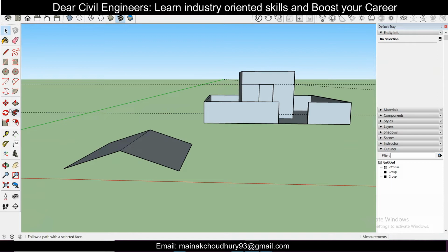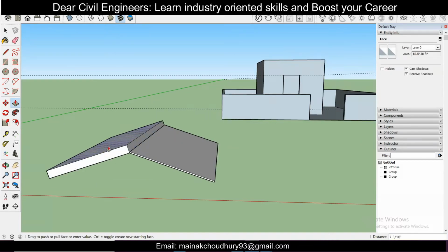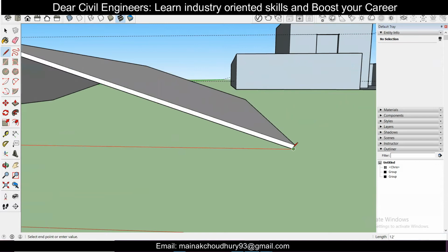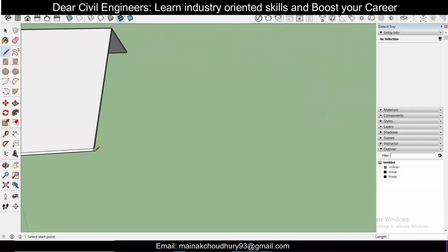So after that, use the push pull tool to provide an offset, let's say 1 inch, and also an offset of 1 inch here. And after that, use the normal line tool, and then just draw, and also similarly connect this.